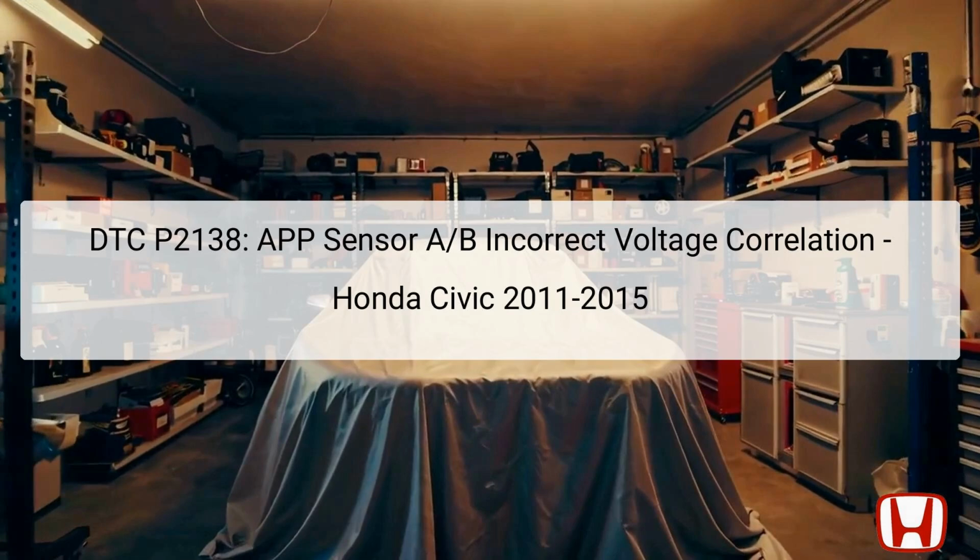The DTC P2138, which stands for APP Sensor A/B Incorrect Voltage Correlation, is a diagnostic trouble code specific to select Honda vehicles, including the 2011 to 2015 Honda Civic. This code indicates that there is a discrepancy in the voltage readings from the Accelerator Pedal Position, APP, Sensor A and Sensor B, suggesting a fault in the system that measures the position of the accelerator pedal.